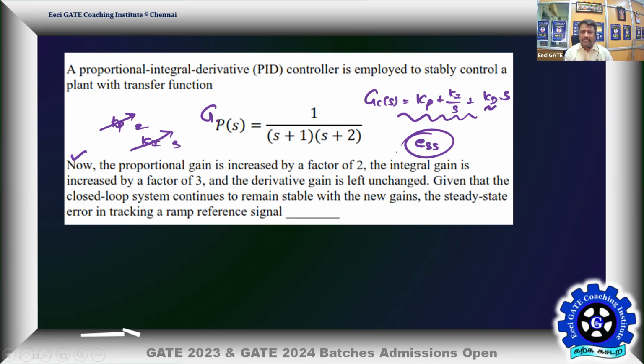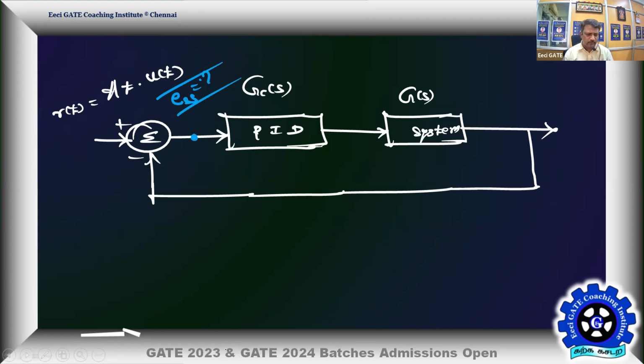Since we have a PID, we are adding a controller to tune the performance; you look for desired performance, but there must still be stability. Since the Kp, Ki, Kd values are not given, you can't investigate stability by using RH. So, given the hint that the system remains stable, you can straight away proceed to the steady state error analysis for the closed loop system.